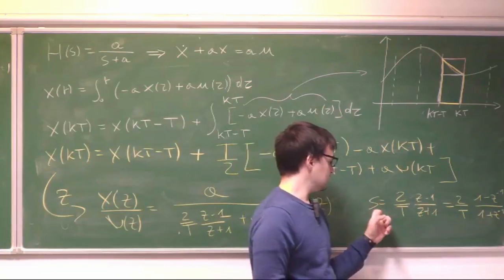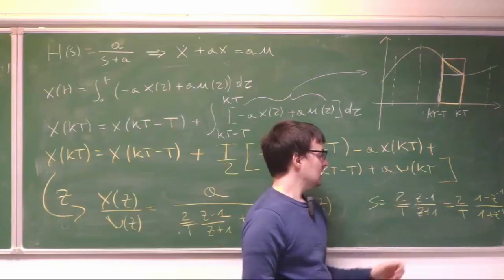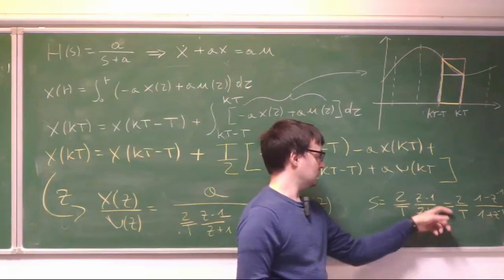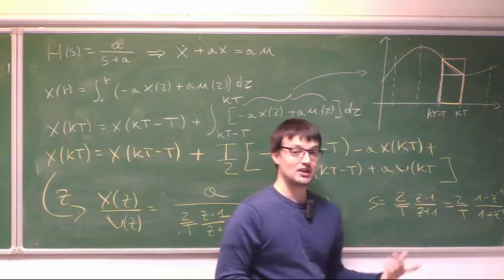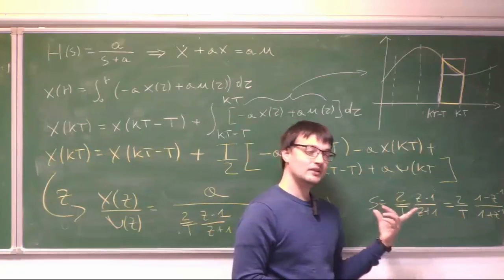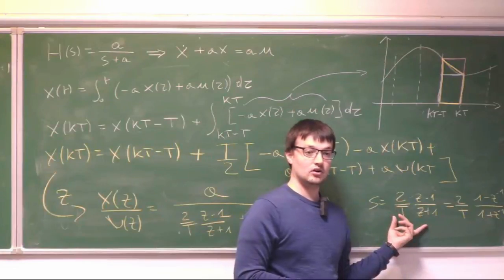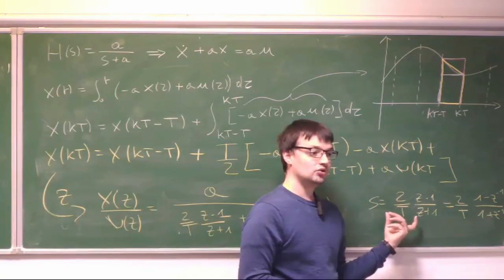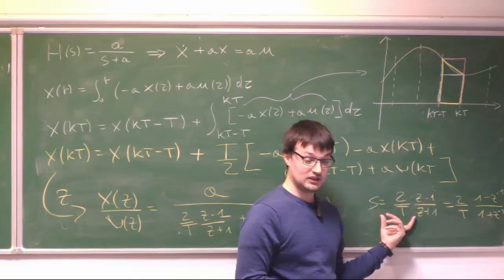Well, you should know at this point because the mapping between s and z has this expression here, and if you multiply left and right-hand side by the denominator, you get an expression that is bilinear in s and z. Okay, so this is very similar to the expression that we saw for the analysis of the stability, the expression that we used to apply the Routh criterion with the w variable.